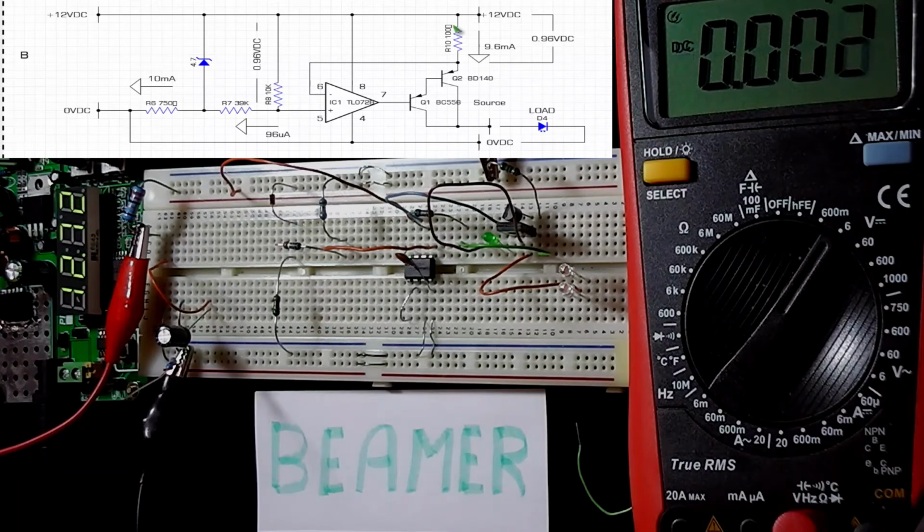You can do that with an auxiliary power supply, but the power supply kind of needs to be tracking. You could do it via a battery or a cell, just lifting it above the compliance voltage of plus 12 volts, making it a slightly higher positive. But I have another solution which I found works, and the next thing I'll do is adapt the circuit slightly so that it accommodates that solution.